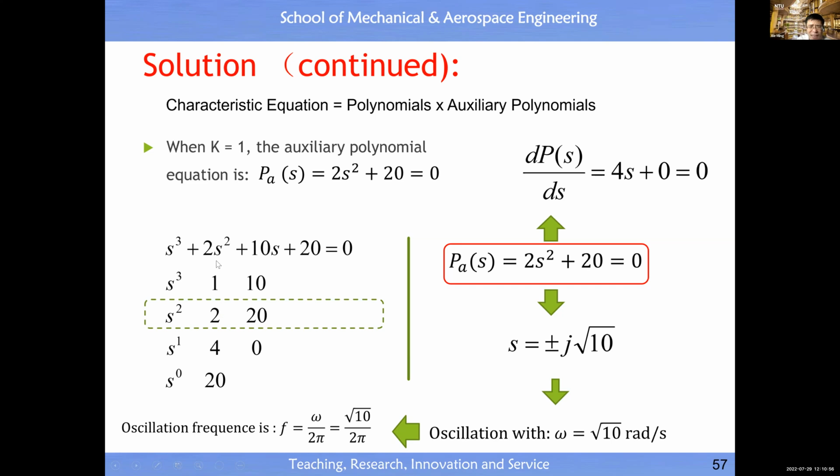Then from here, you see this system is stable, all right? Since this one is part of the initial polynomial or denominator, then we can compute the roots of this polynomial, because this is a simple polynomial. Then the roots are like j omega. For those of you who know control theory, this means there's oscillation.